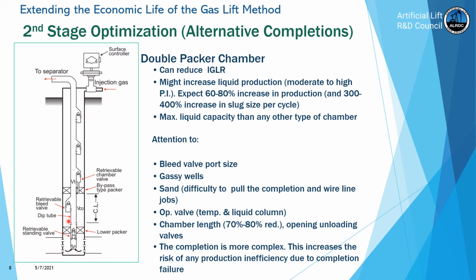So the liquid level here will rise, and the gas that is trapped above it needs to be vented back into the tubing, and from there to the surface. And that's the reason we have to have a bleed valve here.